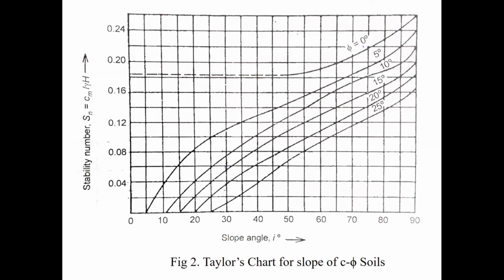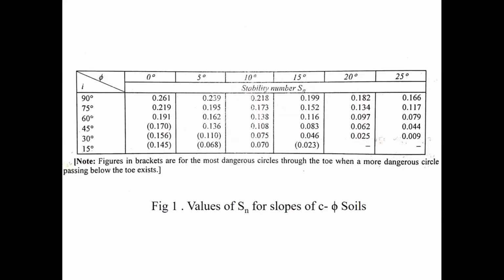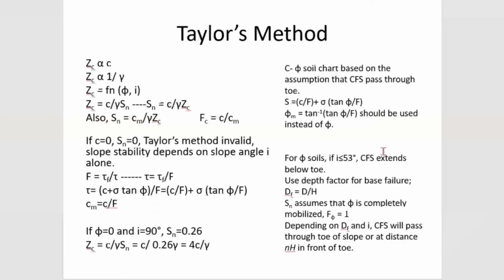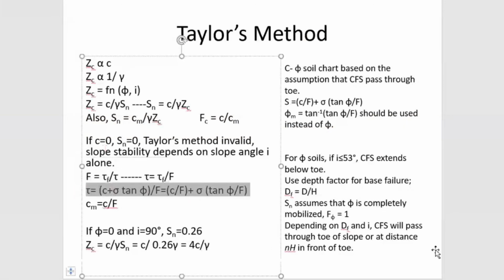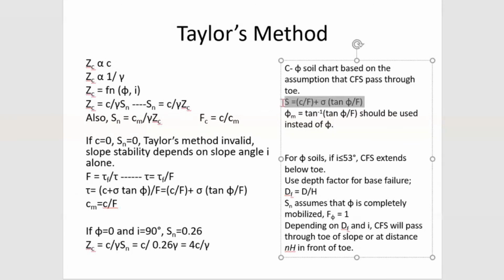So now you have to assume another value of factor of safety, and see whether your factors of safety are almost similar. If it is so, then we can satisfy the basic condition we saw earlier. See here, this is the condition we are trying to satisfy. So your factors of safety with respect to both should almost match. Then you can say that your slope is stable.